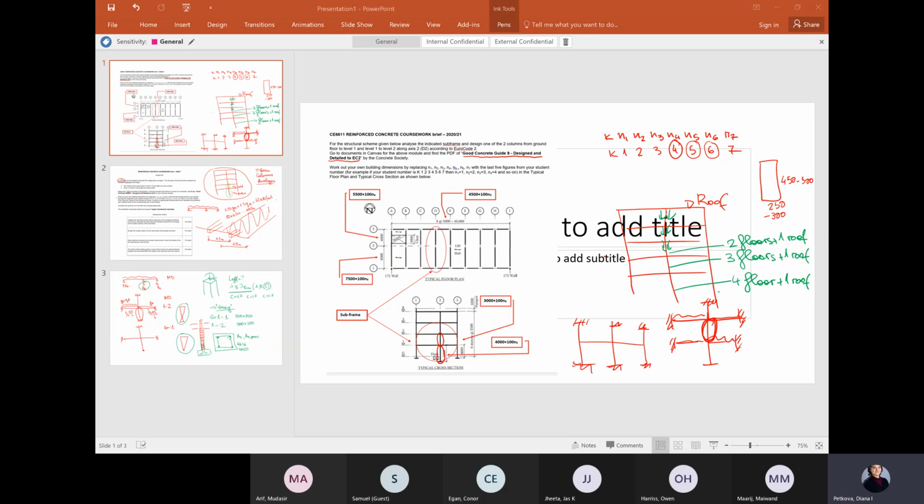Again, the best thing to do is really to express the stiffness of the foundation to rotation, so the rotational stiffness. But we're not going to go that way. So we can either assume that we only have an axial load transmitted to the pad foundation, or we can say that if it's a fixed support, we have an axial load and moment.